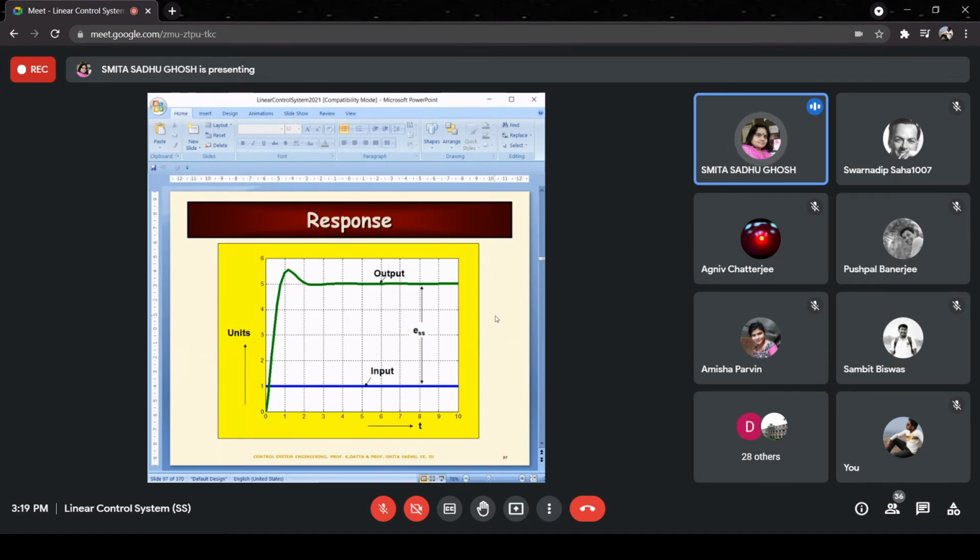Or rather, if I have the conclusion that my steady state error is equal to 0, I can safely say that the output value in the steady state is going to be exactly equal to the input value. Such conclusions are very much appropriate for unity feedback systems. However, for non-unity feedback systems, it would be safer not to attempt such analysis. Numerically it can be done, like I've shown you, but with the caution that you are comparing different quantities and the answers you get may not always be physically significant.